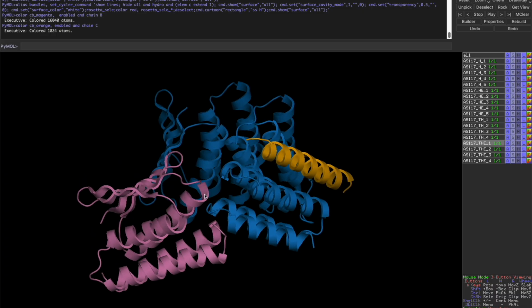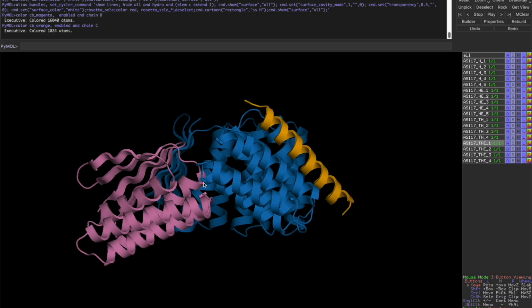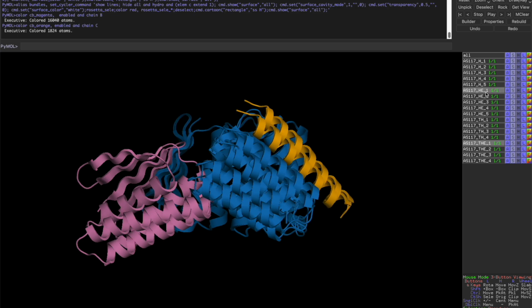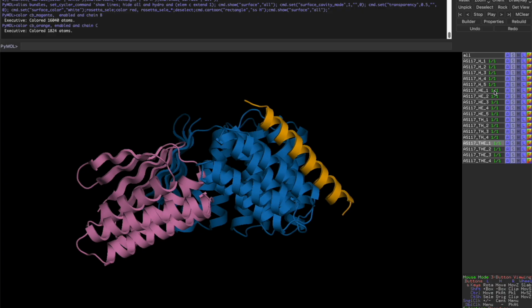So here's one, and this is showing the kind of deformation that I mentioned earlier that in this case was desirable. So compared to the position of the target here, the unstrained position, you can see the target is deforming downwards, and compared to the ideal position of the switch, you can see it's deforming upwards like this, in a way that's putting shear on the secondary structure elements.